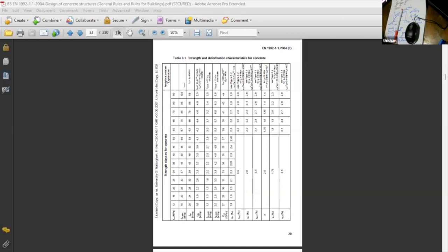Well, we had a problem. The costs were too much. Projects were becoming not feasible. So what we have done is, we have changed the foundation, done a more advanced design. But you might ask, how are you going to ensure that it's going to work? It's so simple. For piles, we have PIT, pile integrity test. We have PDA, pile dynamic analysis. We have maintained load test. So if you take a pile of 1.1 meter, 1.2 meter diameter, do maintained load test, then do PDA on the same pile.